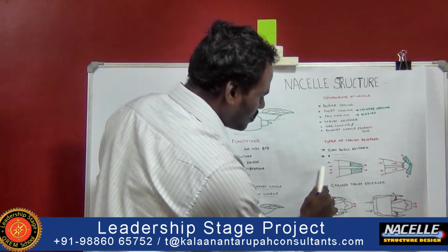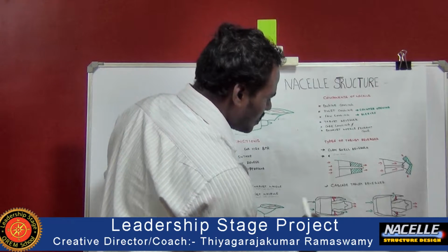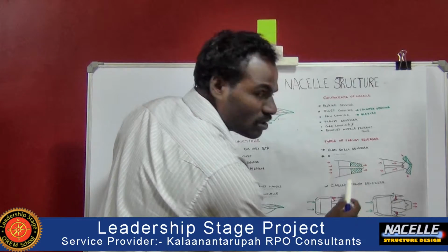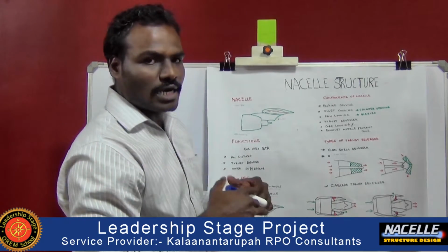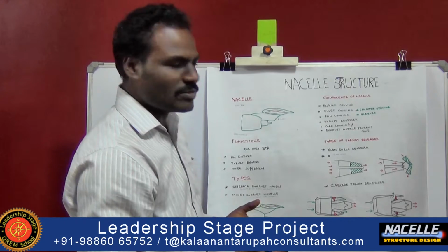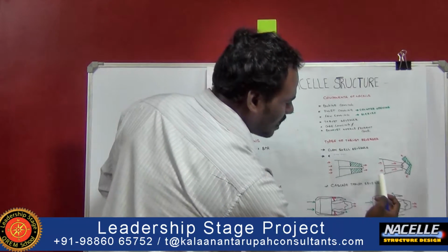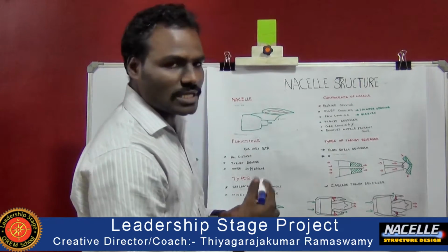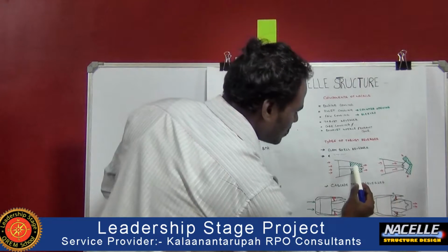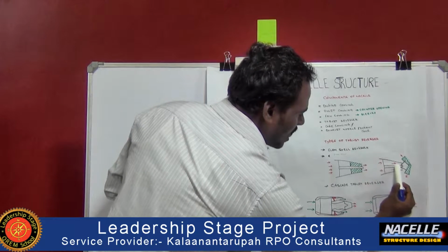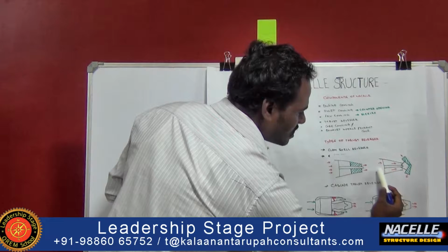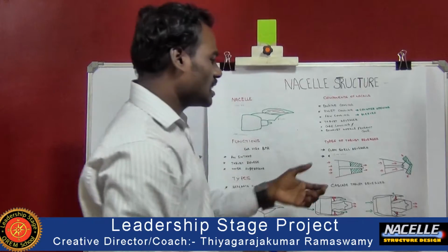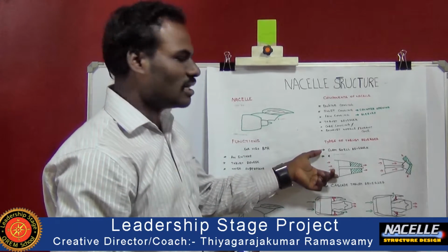When the exhaust gas enters the inlet of the nacelle, the exit of the nacelle consists of scoop-shaped doors, which help us in controlling the exhaust gas from the engine, as shown diagrammatically here. When the thrust reverse process is carried out, these doors slide at this area, which helps us in controlling the velocity as well as the speed of the exhaust gas. So in the clamshell reverser,